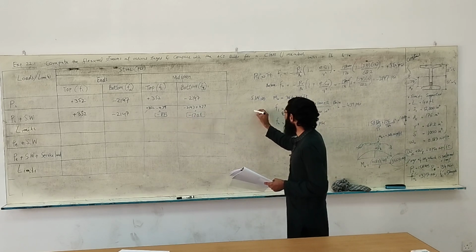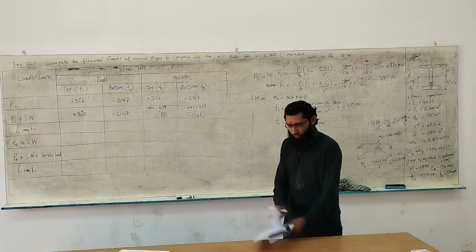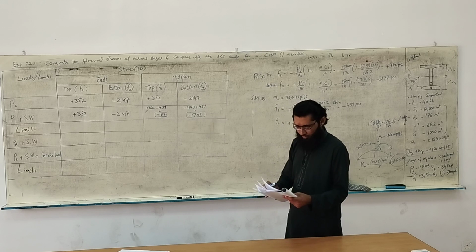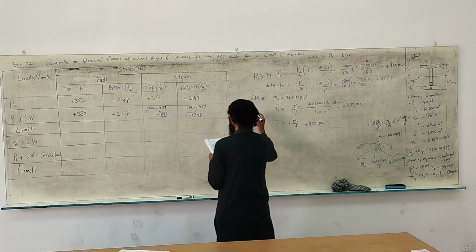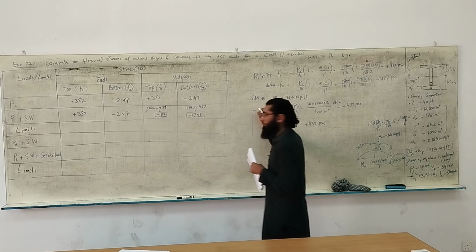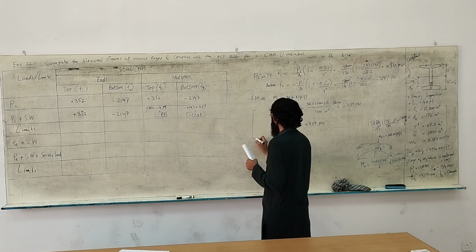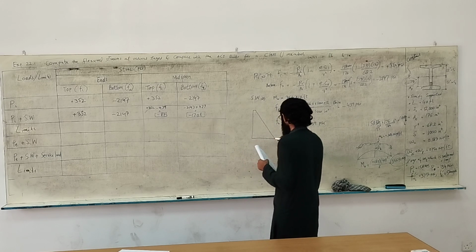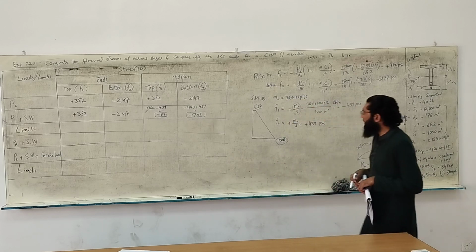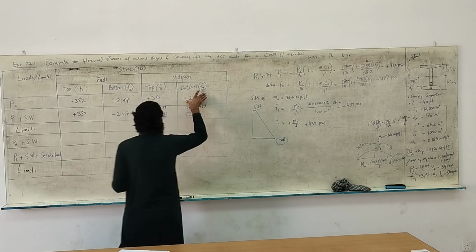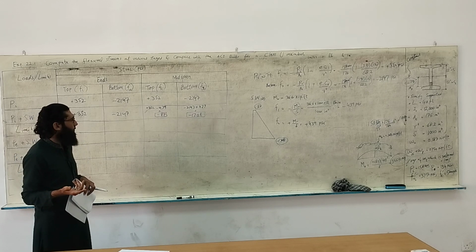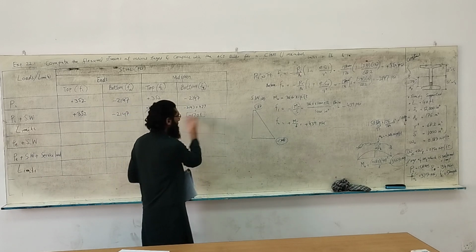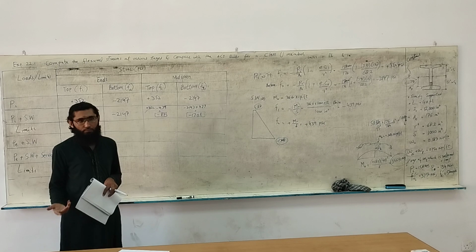If I can just plot them over here for you, it looks like this. Where should I plot the compression? Let me just follow the book's convention. They are plotting compression on the right side. So this is minus 87 at the top, and at the bottom we have a big line to represent a much heavier stress, minus 87 and minus 1708. This is because minus 2147 was a big number for the self-weight to counter. Self-weight is making a little bit of a difference. So it remains compression all over the section, and compression is good for concrete.